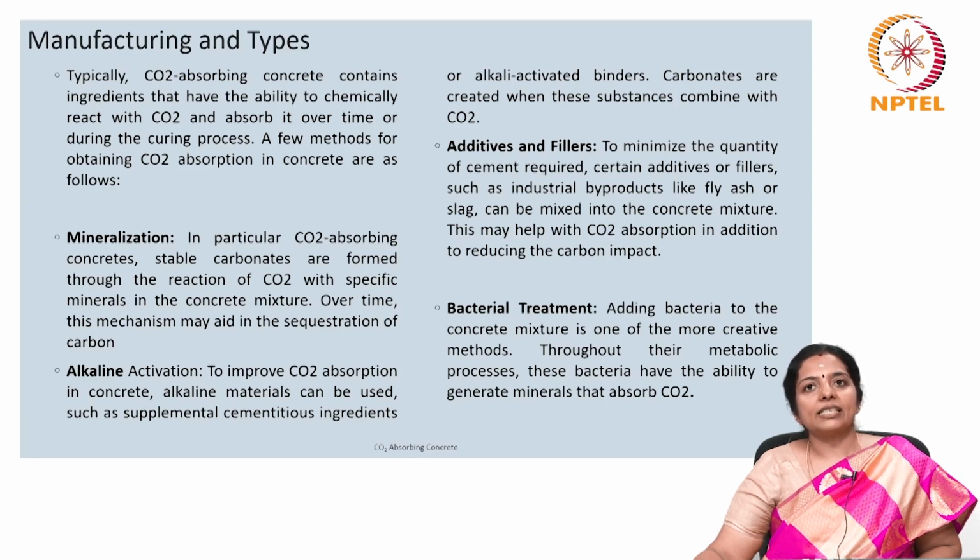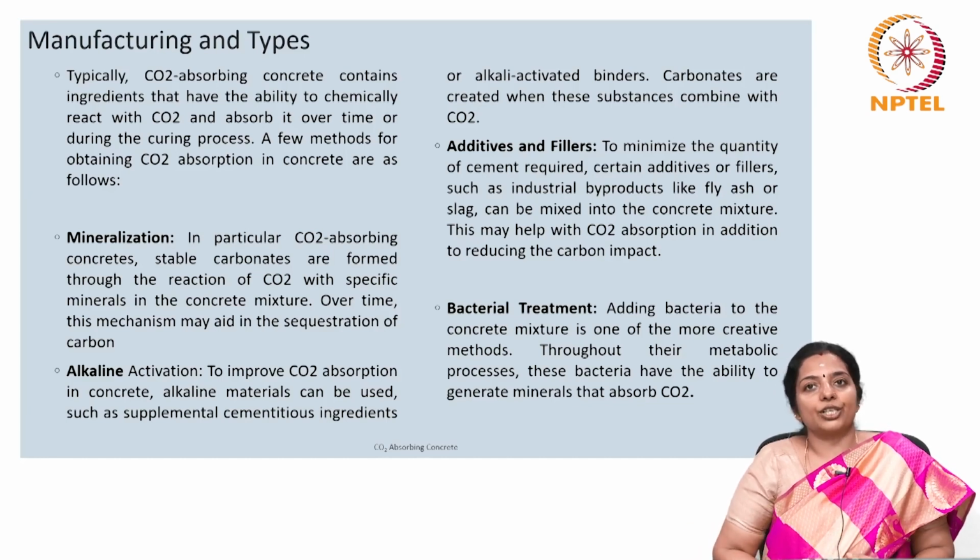Now, first is the mineralization. In carbon dioxide absorbing concrete, stable carbonates are formed through the reaction of carbon dioxide with specific minerals in the concrete mixture. Over a period of time, this mechanism could actually help support and aid in the sequestration of carbon.